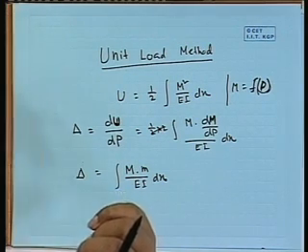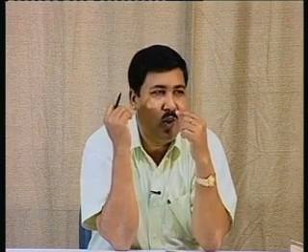Okay. Now, you can say at this point the thing is becoming much more systematic or mechanical. So, if we just follow the steps, we are in a position to find out the deflection and slope. For angle and deflection, only small m we have to calculate twice. Capital M remains the same. Capital M will be fixed, small m will be for different cases. Cases means if I want to find deflection at 2 places and slope at 3 places, there will be 5 sets of small m. Then we have to calculate separately.